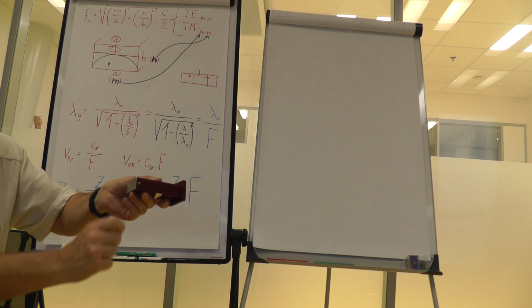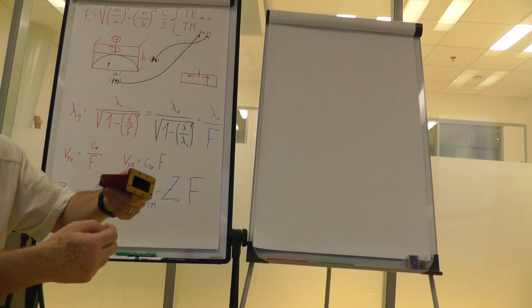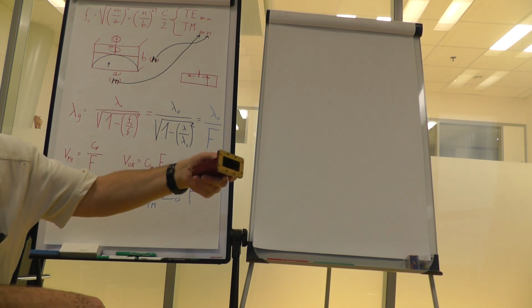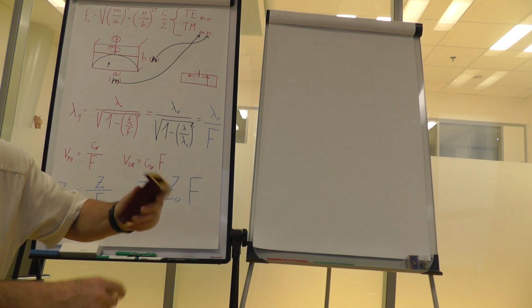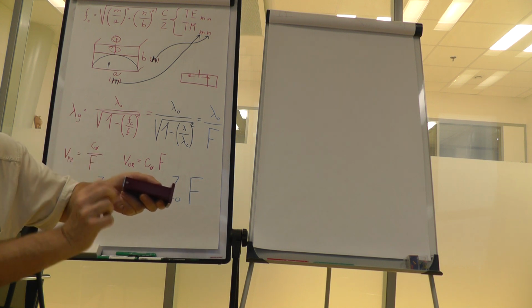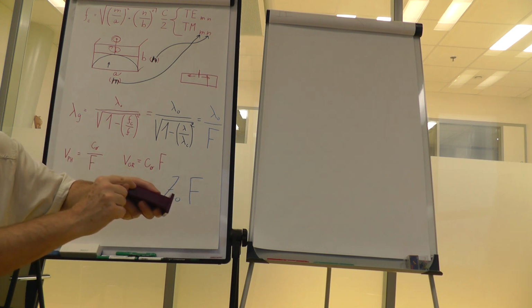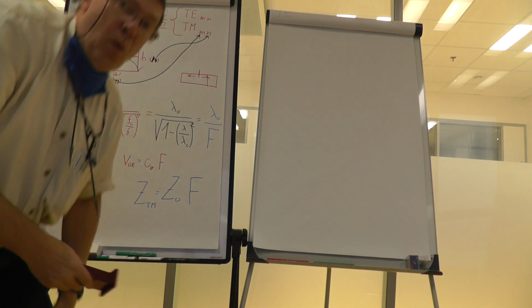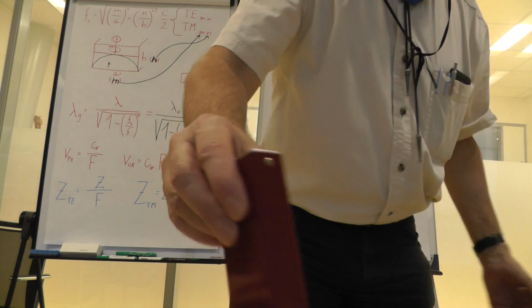It's just in the middle, it's a lossy material, and it gradually eats the wave as it propagates inside. So we have there a thin conical piece of lossy material which causes the wave not to reflect back.